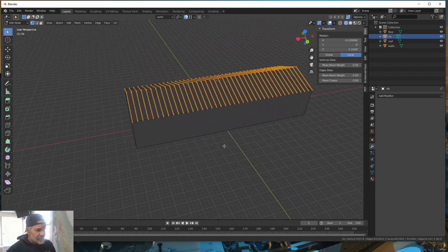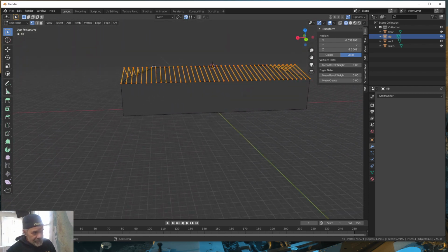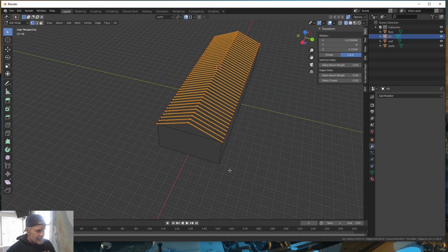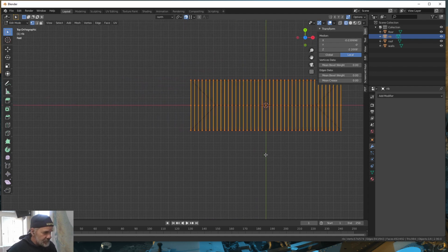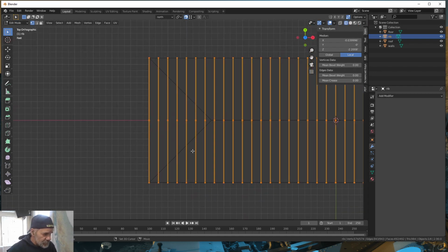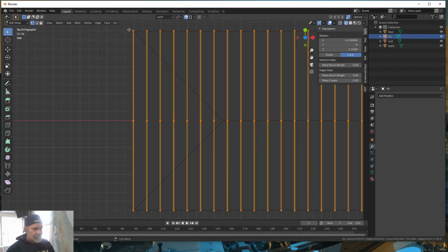Okay, now you notice at the end of the building, the hip comes down like this. So these ribs don't go all the way to the ridge at the ends. So we have to cut those off. How do you cut those off? Well, I'll show you. Let's go into top mode by hitting the tilde T. So we get a top-down view of our building, and we're going to zoom into one portion of our building so we can see this triangle right here.